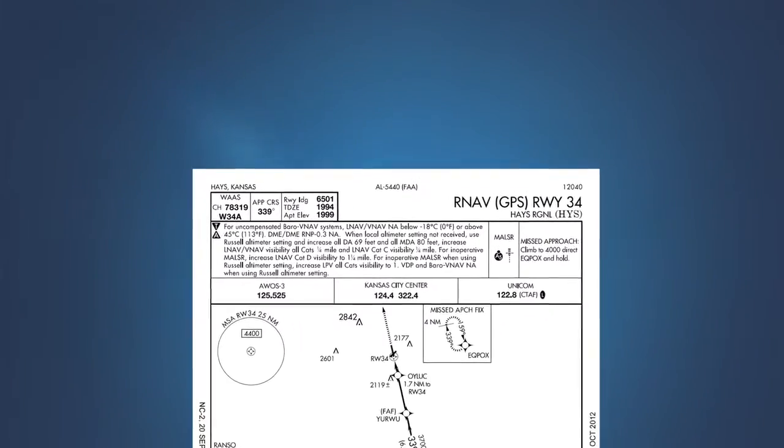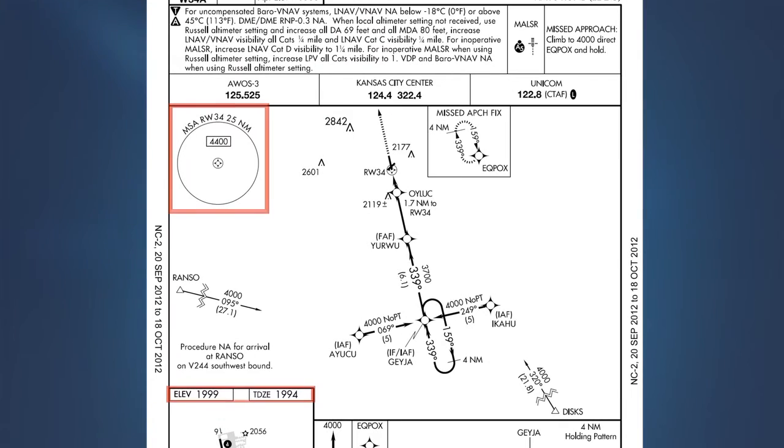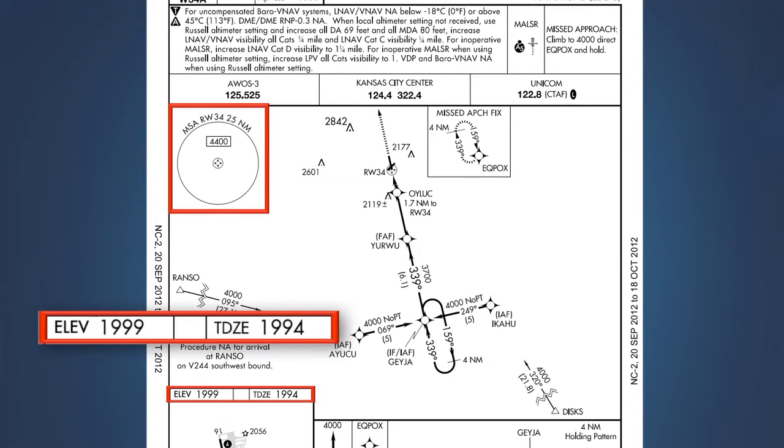When taking off from an airport with limited ATC services or radar coverage, be familiar with the minimum safe altitudes or terminal arrival area altitudes for the approaches serving the airport, especially in the areas encompassing the takeoff and initial climb-out. The MSA or TAA for an RNAV approach is centered on the runway threshold. These altitudes provide at least 1,000 feet of obstruction clearance within a particular sector. Once above these altitudes, a turn back to the airport can be safely accomplished, provided you remain within the maximum distance published for the MSA or TAA.